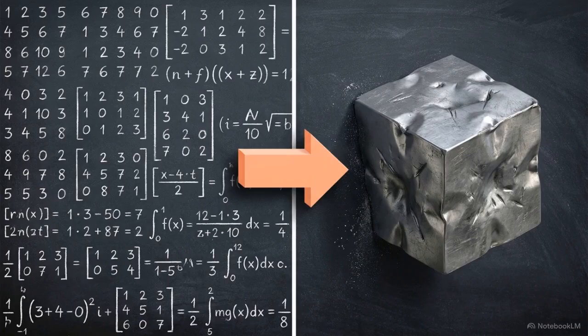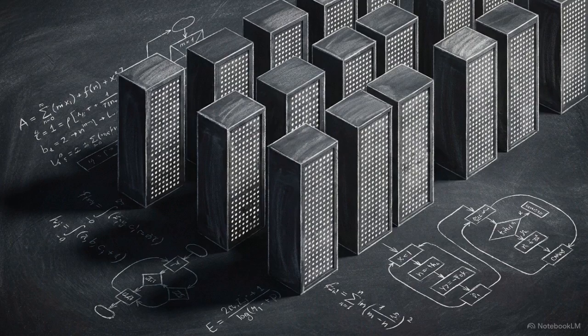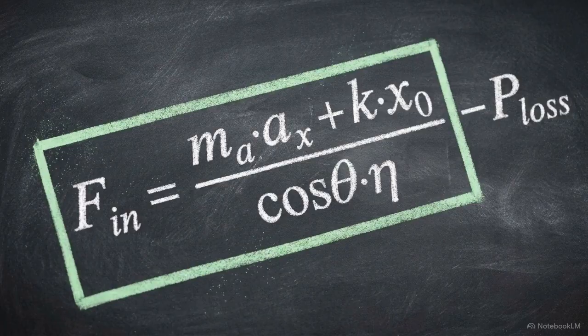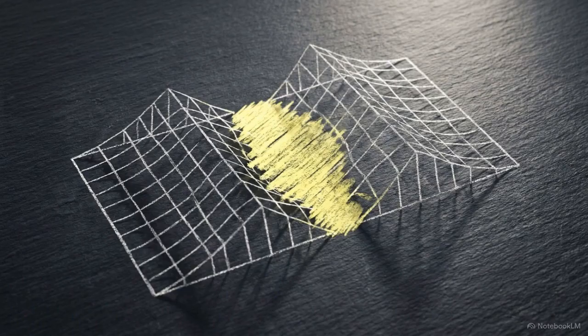The physical geometry of the mesh moves only at the end of this mathematical cascade. Force determines acceleration, which yields velocity, which dictates displacement. Explicit collision analysis involves the repetition of this four-step cycle millions of times per second. The loop executes successfully only if every input force in the equation is known at the start of the step. This creates a specific challenge for the F contact vector.